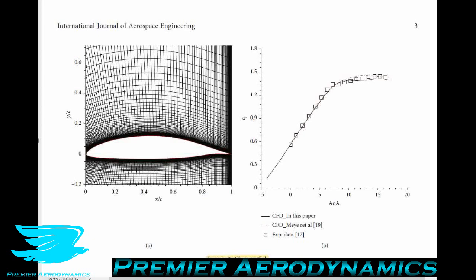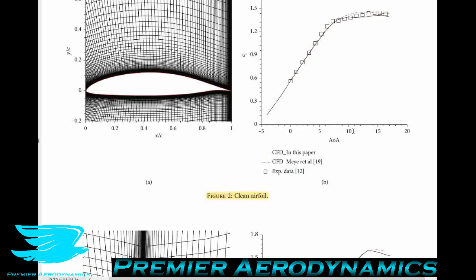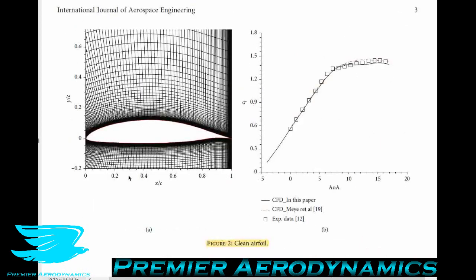Now, one thing that they didn't give us is the drag coefficient validation. And that may be a problem because I'm pretty sure that in the experimental data here, they didn't take into account the changes in the density of air throughout the experiments, because it does change throughout the day and between days, weeks, months, and seasons. So if we have changes in the density of air here, that is then going to change the forces that we measure and also the velocity of the wind tunnel that we're running it at.